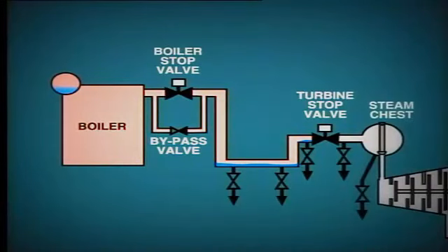This condensate must be removed through the drain lines, which are fitted at low points on the line, including just before the turbine stop valve. Initially, water will discharge from the open drain lines, but eventually, as the piping warms up, this will turn to vapor as less condensate is produced. The drain valves can then be closed, except the before-stop-valve drain, which should be left partially open. During this time, the pressure in the pipework should be building to a level equivalent to the boiler pressure and allow the boiler stop valve to be opened.